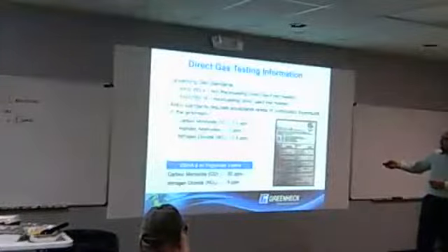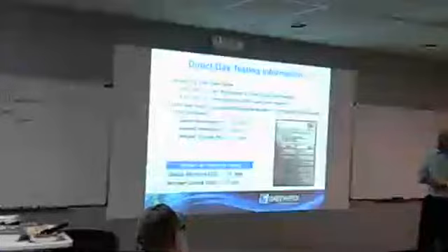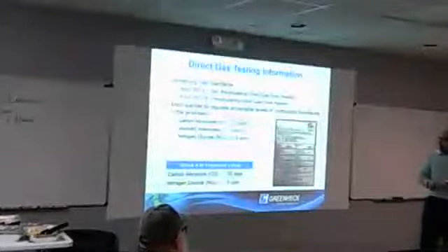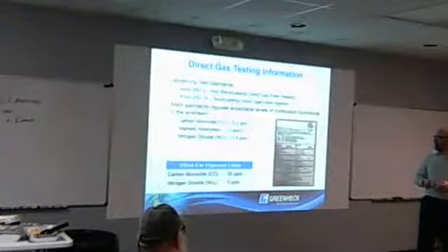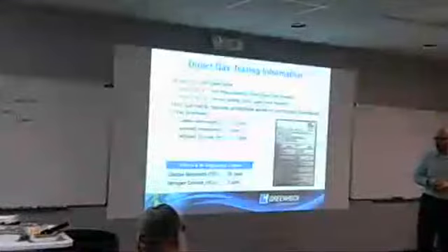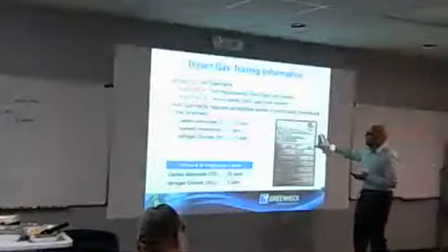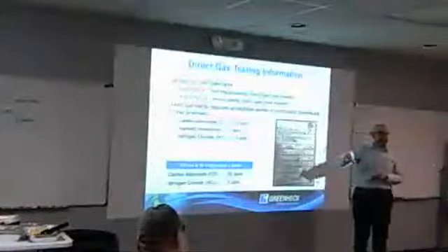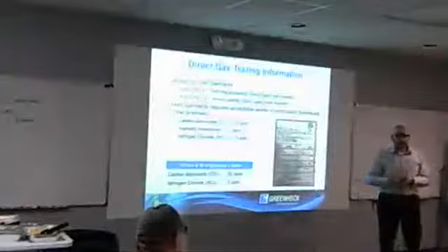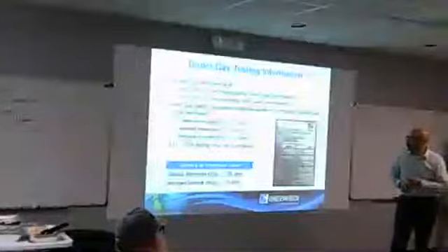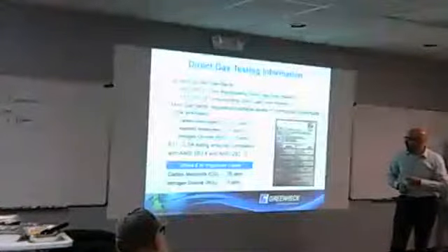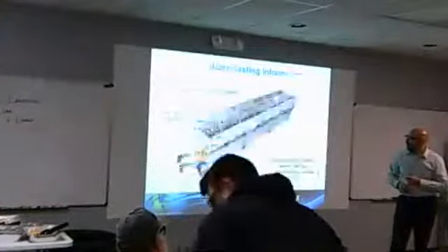So in terms of levels of combustion products, carbon monoxide, 5 parts per million, aliphatic aldehydes, 1 part, and nitrogen dioxide, 0.5. So that's when the burner's tested and you receive your ETL listing by the manufacturer, that's what they're testing against, if proper combustion is occurring at that direct gas fire burner. ETL ensures compliance with those standards.